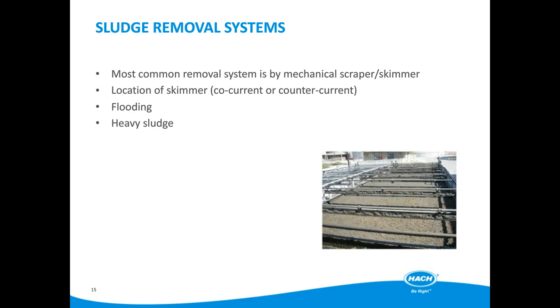Some manufacturers prefer countercurrent removal direction, with the idea that the major solids removal occurs directly above the sparger, this being where the bubbles are introduced, and hence the most sludge would be likely to be formed. In this orientation, the idea is that the sludge is removed quicker and has less time for the bubbles to detach, causing larger sludge particles sinking to the bottom of the tank.